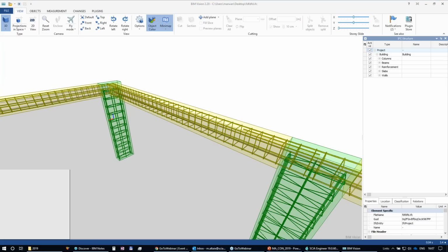A nice question. The question is, does SCIA calculate the required reinforcement based on the crack width? I will mention it again. What we have today is for the ULS. All the calculation of the reinforcement for 1D and 2D members today in SCIA Engineer is for ULS, so there are no cracks in the background.